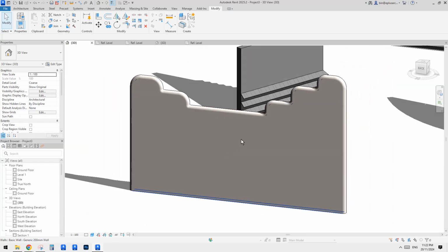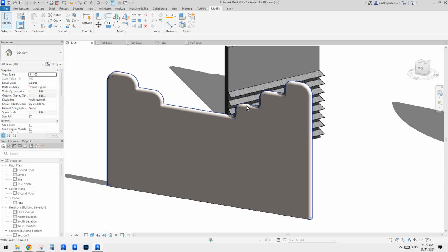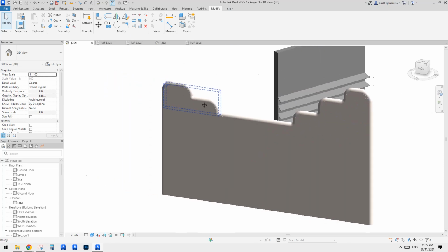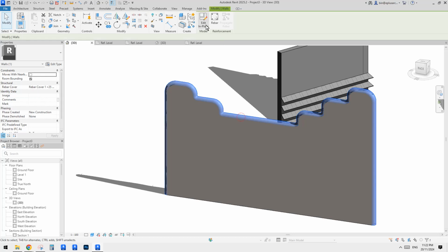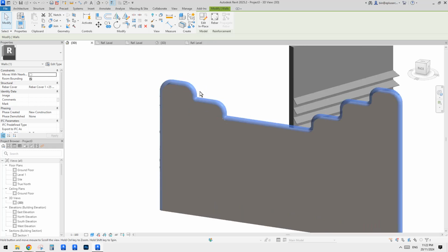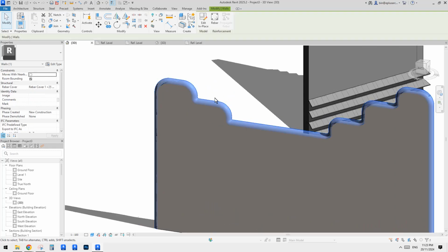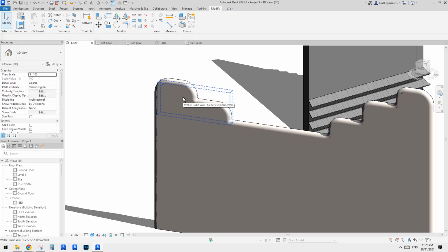And still, the reason why I use pick path for the sweep is, if we need to change the shape of this one, we don't need to go into the modify, edit in this model in place model, because it should automatically change to match the wall.